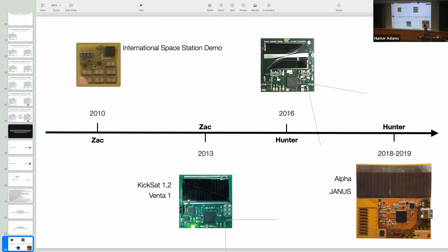And so the addition of these torque coils allows us to generate a magnetic moment in space that interacts with the Earth's magnetic field and causes a torque. That gives us the ability to do a little bit of orientation control of these things. Essentially, you deploy them spinning, you generate a magnetic field, you feel a torque from the Earth's magnetic field, and you can make it precess about the Earth's magnetic field. So you can kind of reorient them.